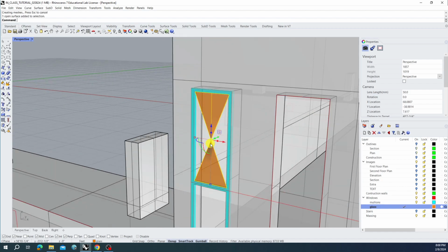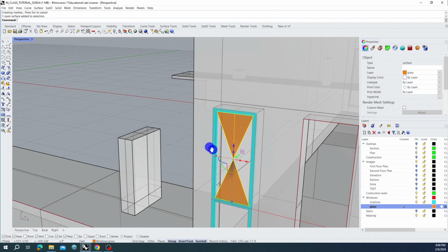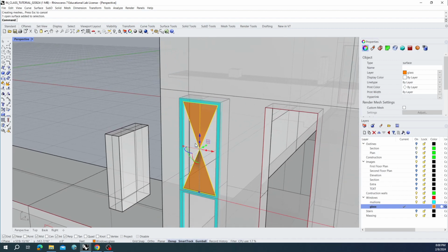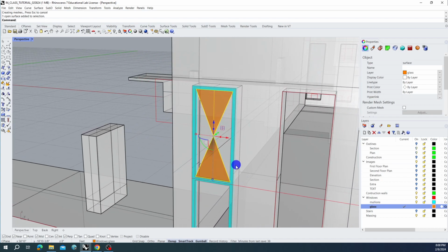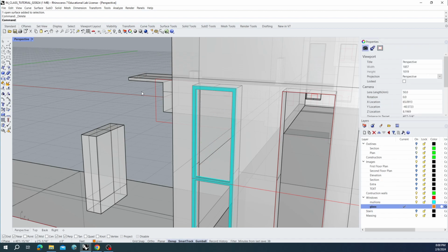So what I did there is just create a bad surface. That can be a problem. You need to make sure that when you're creating these things, you go in order. You see, I went from the bottom left to the right to this top left, so I crossed the path. But I should have gone from the bottom left to the bottom right, to the top left. I was going to go and delete that and do everything a different way, which may be a little bit simpler for everyone.